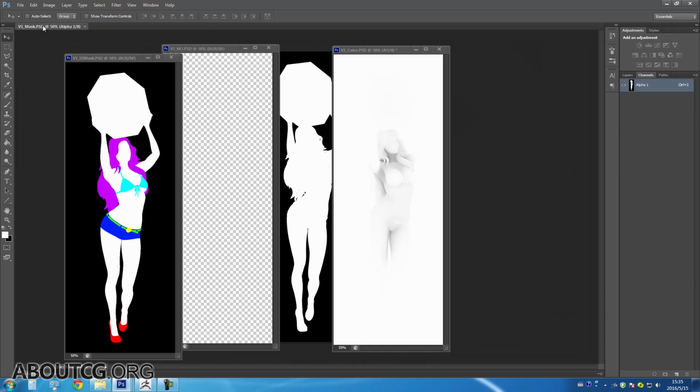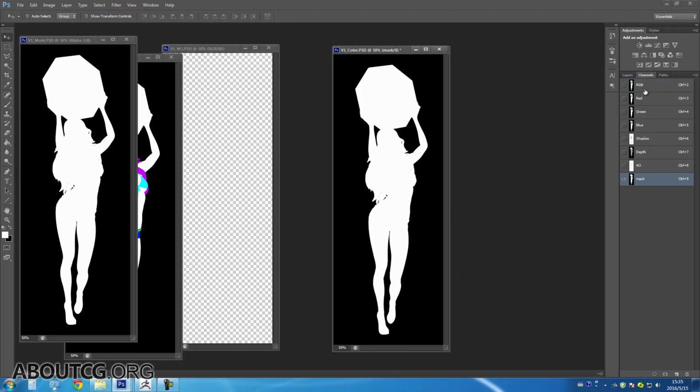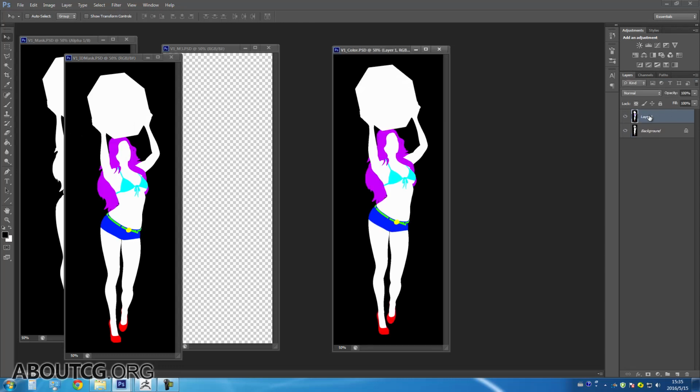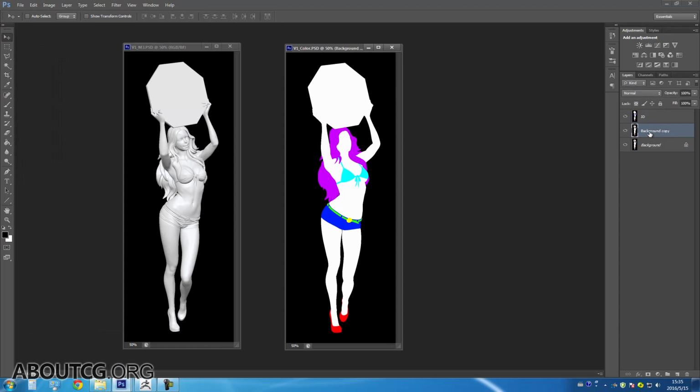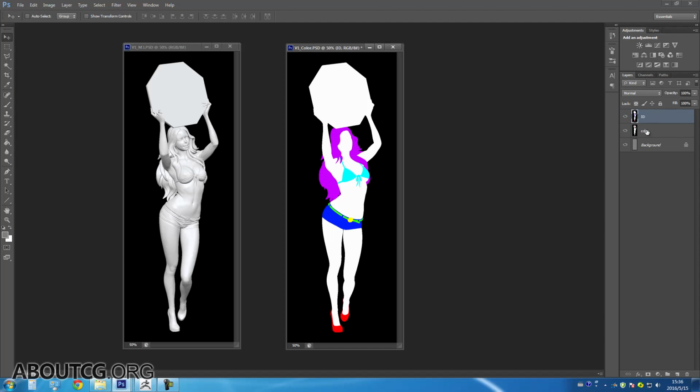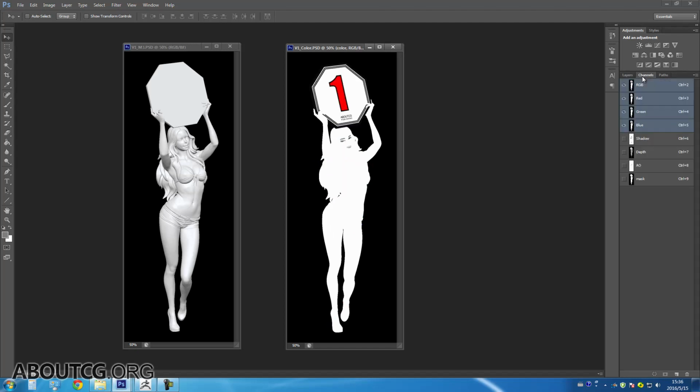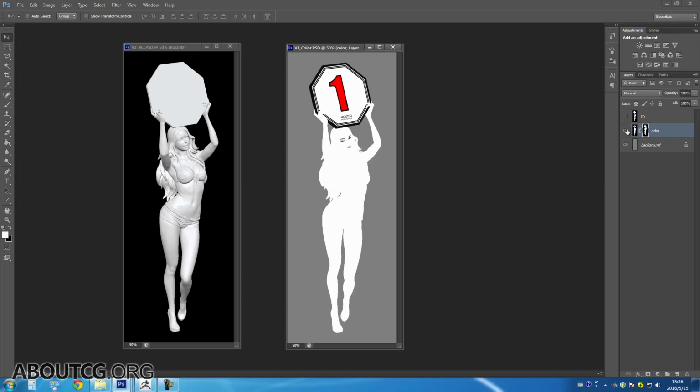Next, we'll take this M2 and import it. Similarly, apply a mask and name it. We can use some overlay properties for this to see what the effect looks like. Generally, our overlay effects are usually in overlay or soft light. For hard light, you can see, after adding this texture, the whole object will appear more stable and have more weight, so you can also see, it comes with an orange attribute. We can adjust the hue a bit, including its purity, to intervene in this color, to see if it needs to be biased. What kind of effect?